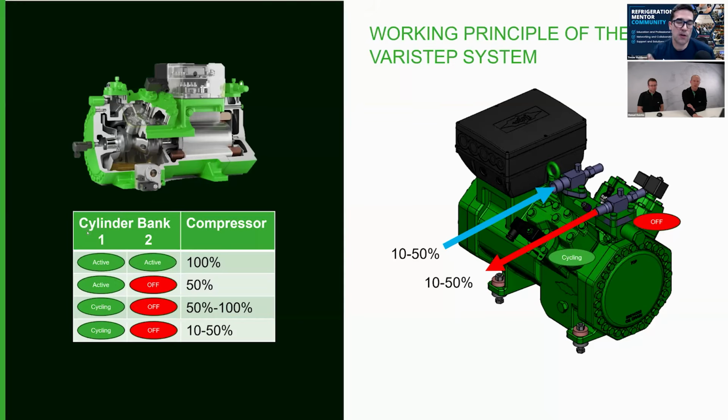So would it be the same with this? I know in a lot of your documentation on your fixed compressors, we want technicians to check the cylinder temperatures, right? One cylinder versus the other, because one could be damaged. So if they're all closer to the temperature, are they going to do the same check on the Varistep setup? Checking the discharge gas temperature with the Varistep is a little bit more challenging, especially when we go below 50% of operation, because we don't see a constant mass flow, and therefore we will always see a peak and so on. Therefore, we have this on the later slides also.